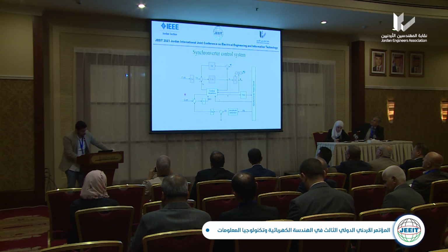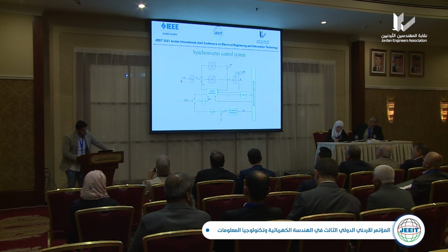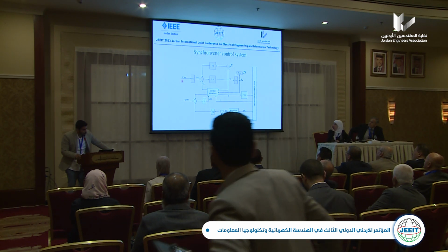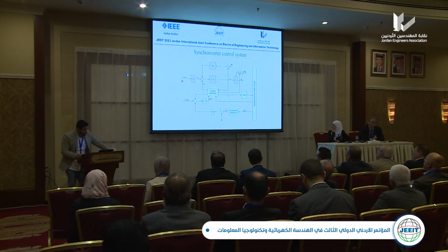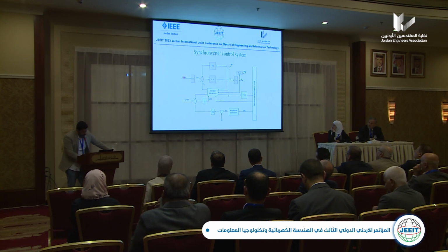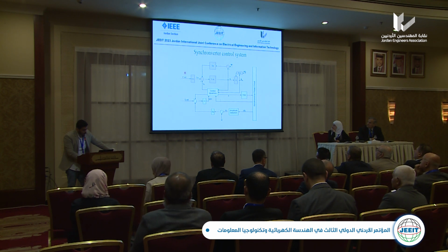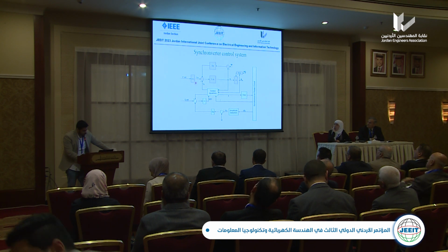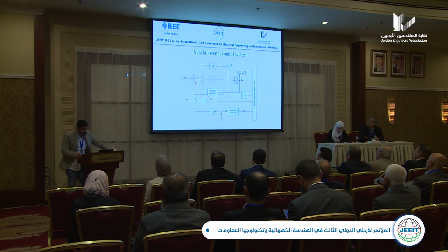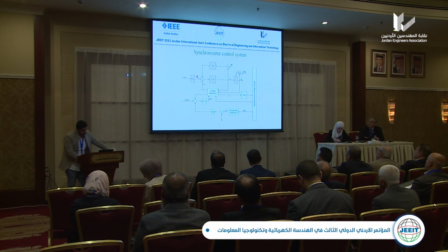Here in front of us we have the synchronverter control system, which consists of 2 loops, the upper control loop and the lower control loop. The upper control loop consists of the reference active power that we hope to achieve, multiplied by 1 over omega n, the virtual angular velocity of the virtual synchronous generator, and gives us the mechanical torque, which enters the summation point here.